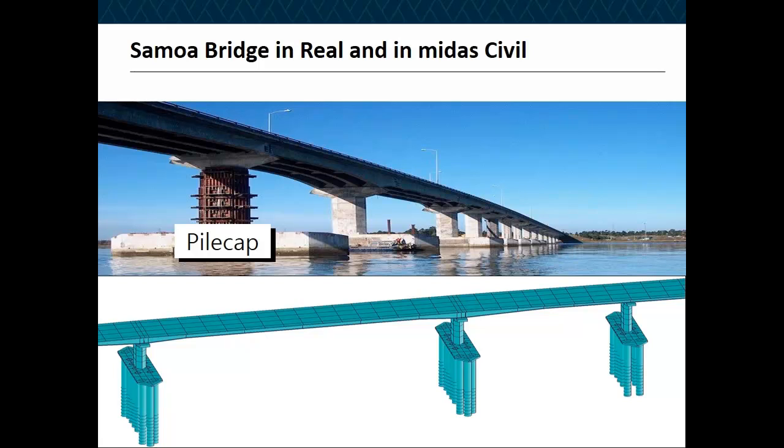Now, the pile caps are very massive. This is actually part of the retrofit that we were doing. The retrofit actually was done in early 2000. Here is a pile cap which is very massive with the pile foundation. For this type of a structure, the modeling of the pile cap, correct modeling, correct dimension, correct mass of the pile cap is extremely important because it's a dynamic system and mass comes into play.